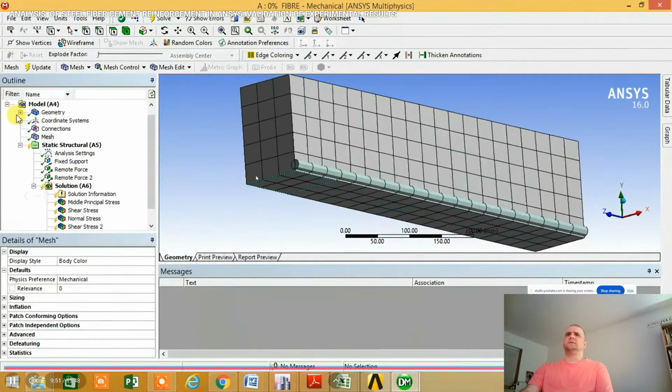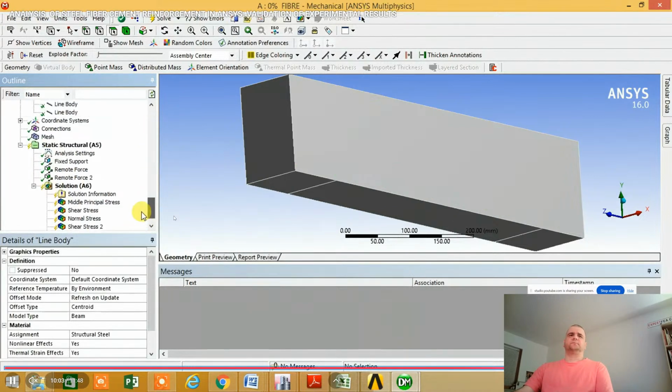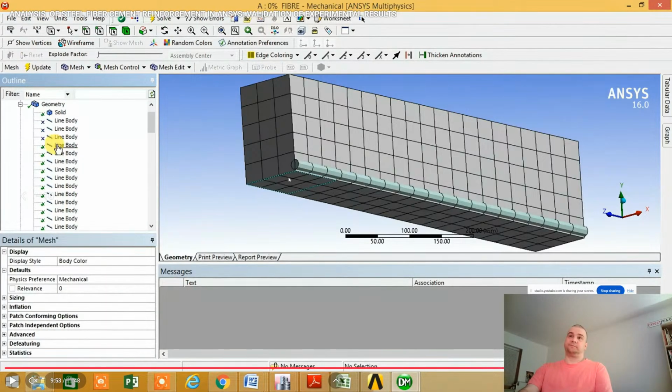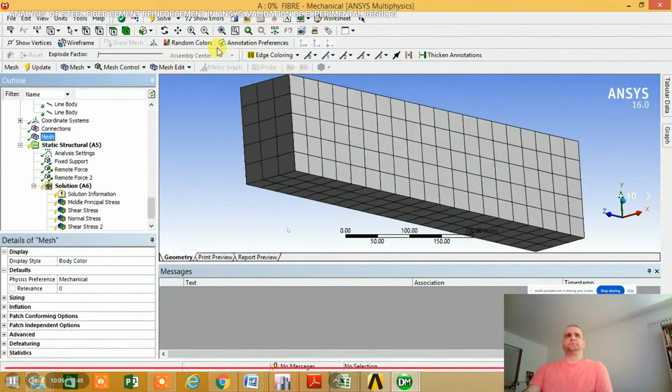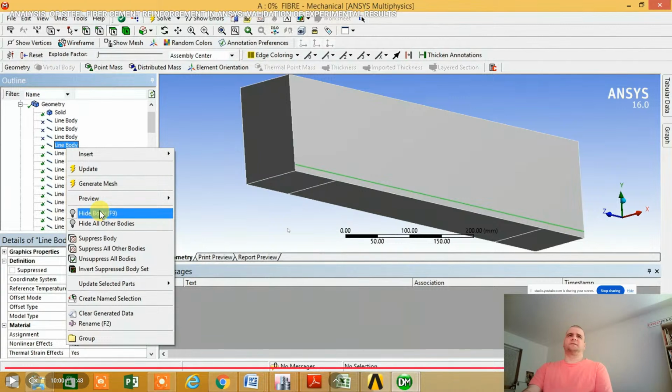Oh, is something sticking out? Yeah, he inserted this exactly near the face. So the profile of the reinforcement of the rebar is so big, the diameter, that it exceeds the geometry. So yeah, this is too big. It's not realistic at all. What did he do? He hid this body. So he didn't remove it from the FEA. He hid it.